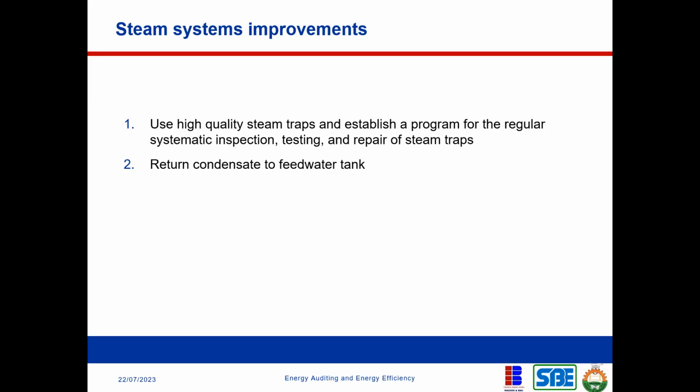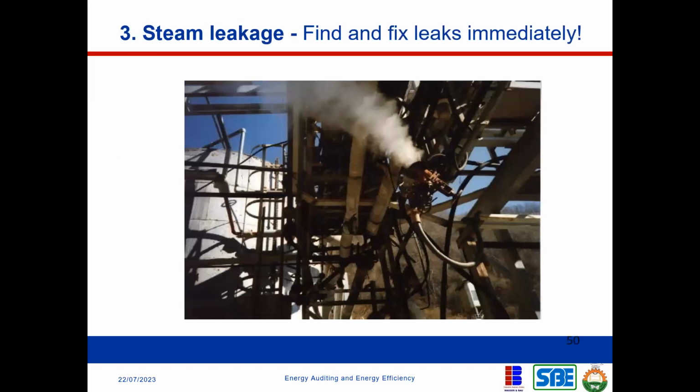So steam system improvement: use high quality steam traps and establish a program for regular systematic inspection, testing and repair of steam traps. I already talked about this. Return condensate to the feed water. Now, sometimes you also have steam leakages in your steam distribution system.